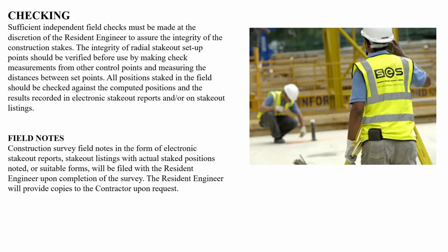Field notes. Construction survey field notes in the form of electronic stake-out reports, stake-out listings with actual staked positions noted, or suitable forms will be filed with the resident engineer upon completion of the survey. The resident engineer will provide copies to the contractor upon request.